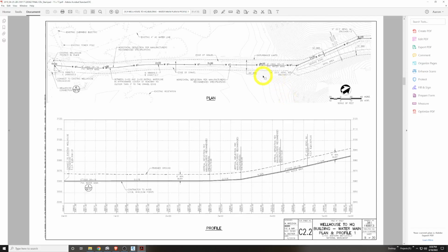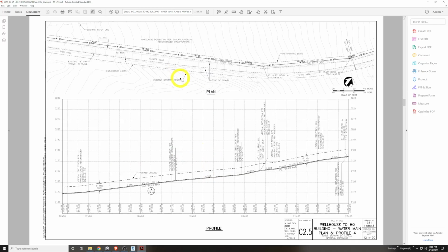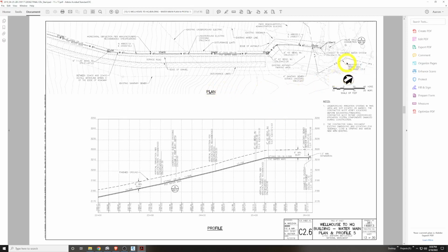And yeah, here is our typical ending result of some of these: a plan view and a profile view showing your pressure pipe. In this case, a 6-inch water main PVC pipe of that material going in a plan and a profile view with your elevations and stations associating it in the horizontal and in the vertical. And here they correspond together as it goes up the alignment, further up, and it's going uphill, and it's showing in the plan and profile view. And here's our final PDF that just kind of depicts all of this. So we have our limits of disturbance and various other things in here.